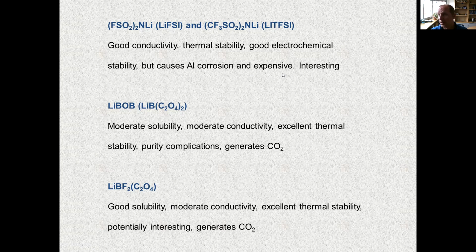Another problem with these is they're quite expensive, much more expensive than LiPF6. Now, LiPF6 itself was a very expensive salt earlier on in its investigation. However, as the salt was scaled up, the cost came down, so it's not inherently a problem with these materials, but at the moment, it is a concern. As I said, lithium bisoxalatoborate, LiBOB, has moderate stability, moderate conductivity, pretty good thermal stability. It's had some purity complications, and one of the biggest problems is that upon reduction on the anode side and also oxidation on the cathode side, the oxalate species are converted into CO2 gas, which causes cell gassing, which can cause cells to swell and hurts the overall performance.